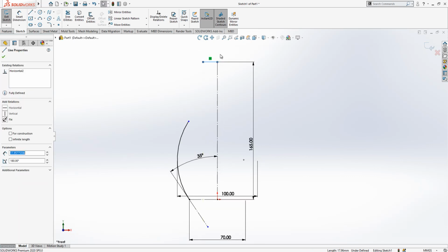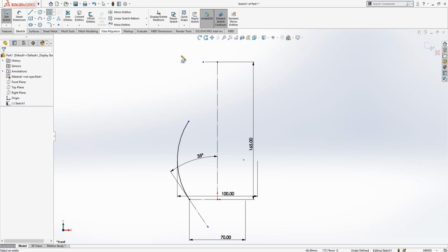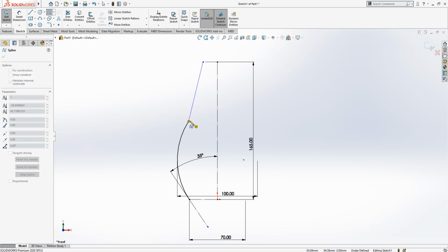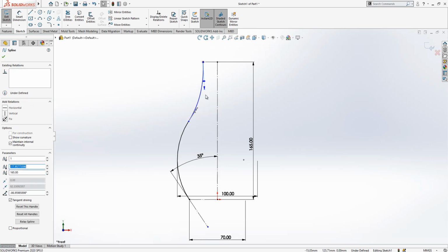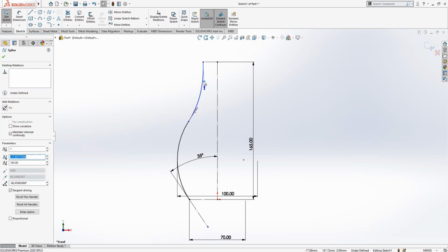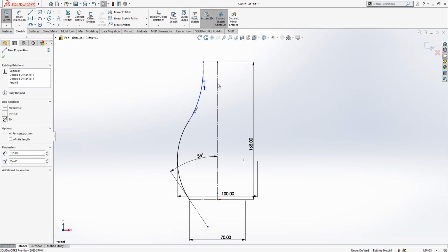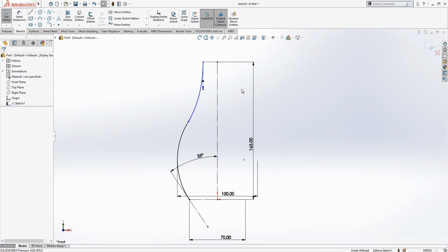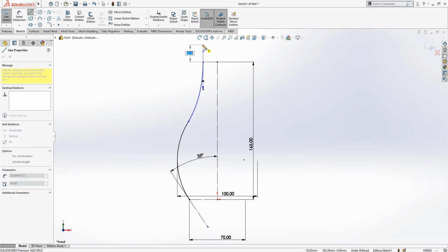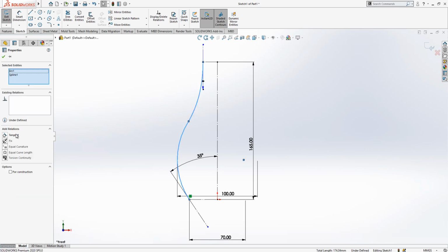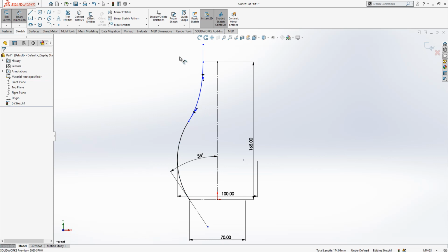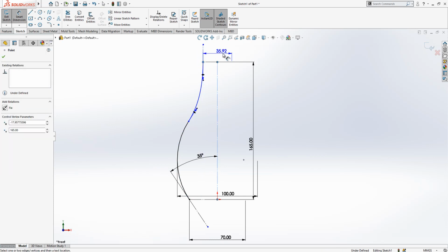Here I create a line, and on this line I place a spline. I'm just showing my spline control points. Control is clicked and this point, this tool selected, and also vertical line, and we make parallel. Maybe you have seen before, sometimes I do create a line and just giving a tangency, the same operation gives you the same result. And here we have a diameter of 10.